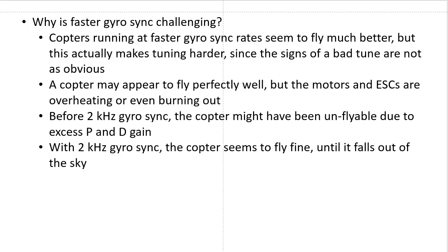So if you're going to 2 kilohertz, I know Boris has come up with defaults that he feels are good for most people, but my recommendation would be that anybody flying on 2 kilohertz for the first time definitely treat it as a completely new tune and try to start with very low P and D gains. Take off, do a 10-second flight, land, and check your motors, or more importantly, have Blackbox.